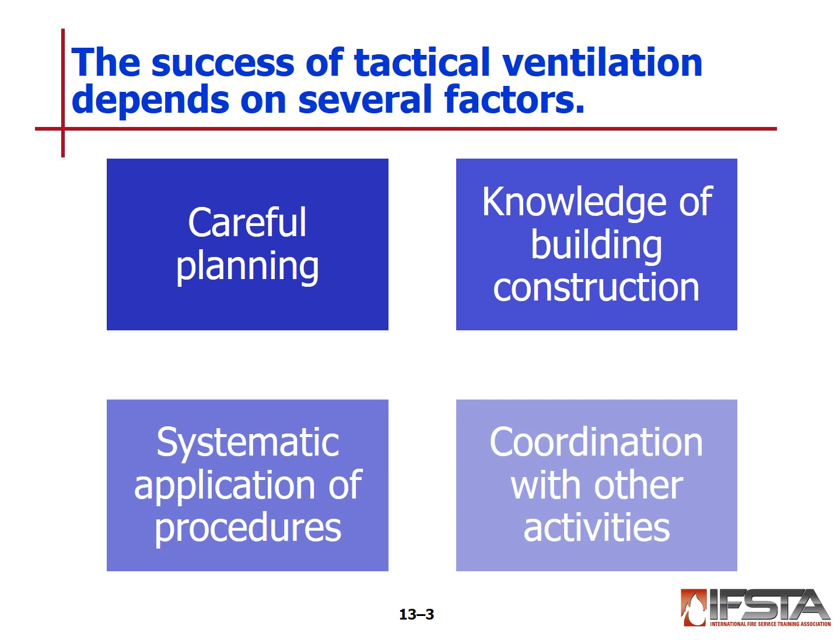Knowledge of that building and the building construction itself. Is it just a single family residence? Is it a multi-dwelling? Is it a commercial structure? And that's where a lot of your pre-planning will come into play. If you get an opportunity as part of your fire department and you're looking for something to do on training nights, go out and do pre-plans of some of your structures that you feel may be of high risk. Or maybe just ones that, if something were to go wrong, even if it's not high risk as a fire threat, are high risk for your safety.